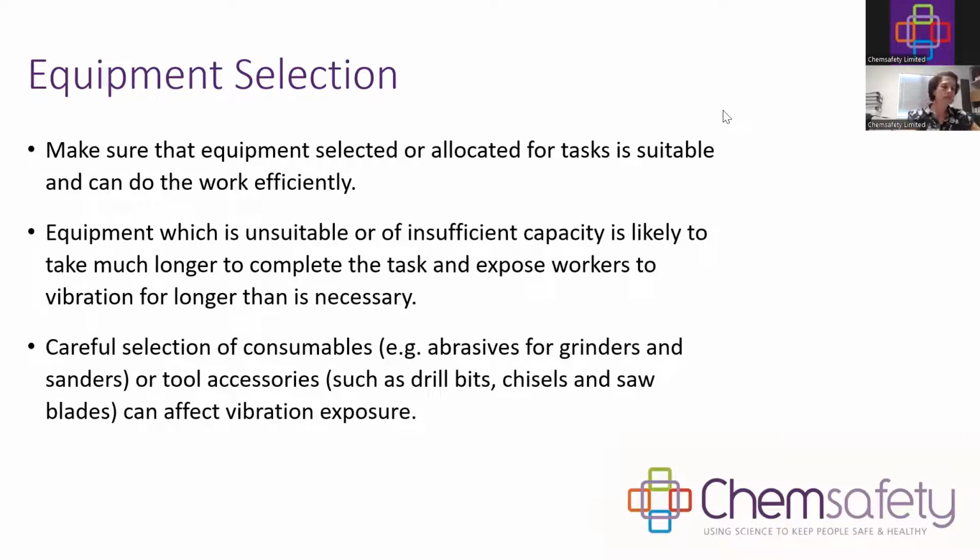So when you're selecting equipment, it is important that you make sure that the equipment selected and allocated for the task is suitable and can do the work efficiently. Because if the equipment is unsuitable, you might have to do the task longer than expected, and thus you are exposed to the vibration longer than is necessary. So it is very, very important that you also carefully select other consumables related to your tools, such as abrasives for the grinders and tool accessories such as drill bits.